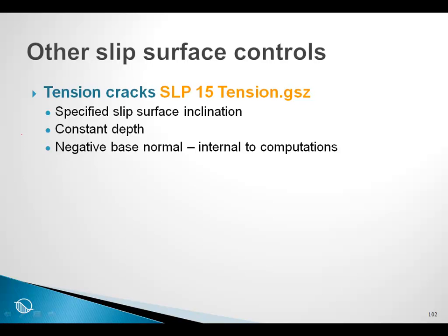One of them is to specify an inclination angle. If the slip surface becomes too steep, a tension crack is automatically incorporated into the analysis.